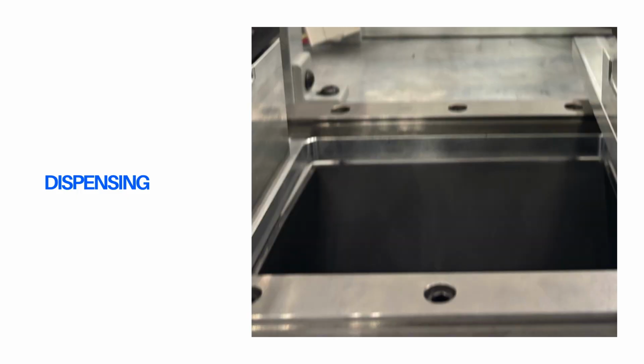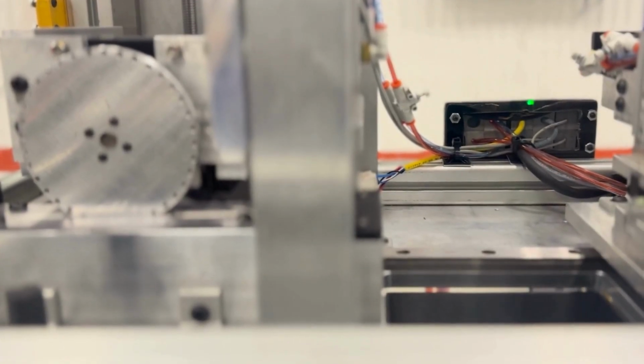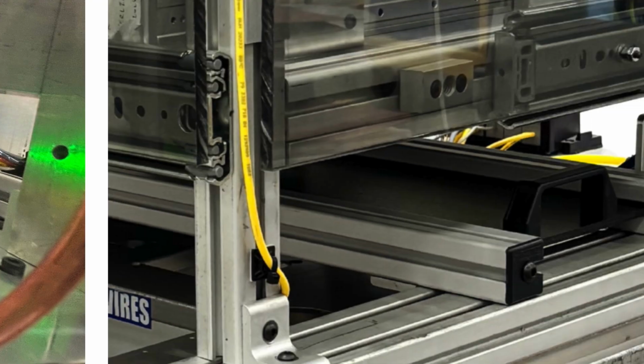Dispensing subsystem. After the cut, the linear servo performs an over-travel motion. The pneumatic grippers open, releasing the thread into a 3D printed funnel drop slot, assisted by an air blow-off line. The finished thread drops into an external tray for immediate operator retrieval.